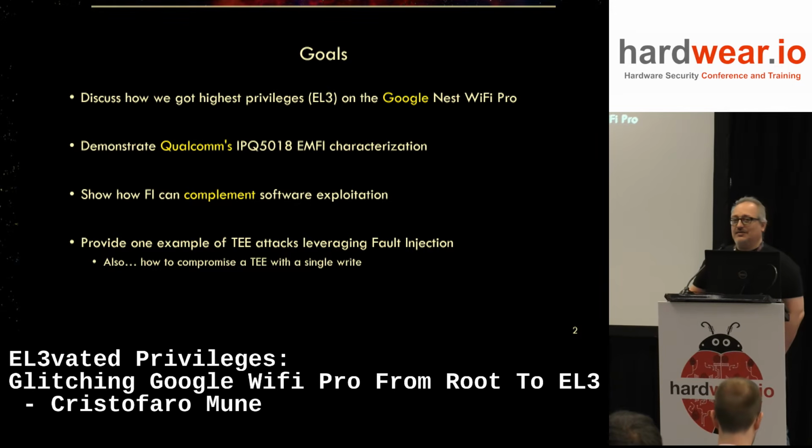EL3 is basically the highest privileges on the device in an ARM TrustZone based device, which is the case for the largest majority of devices nowadays. Basically, we are going to do this on the Google Nest Wi-Fi Pro. We are also going to discuss EMFI characterization of a Qualcomm SoC, which is at the base of the Google Nest, which is the IPQ5018.